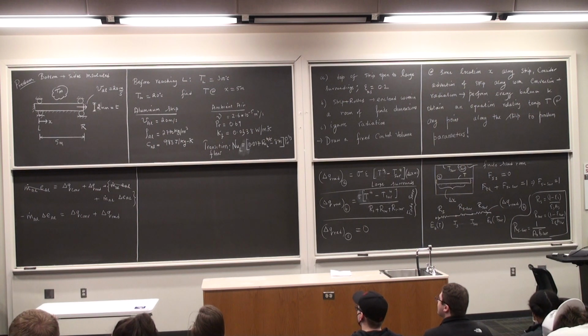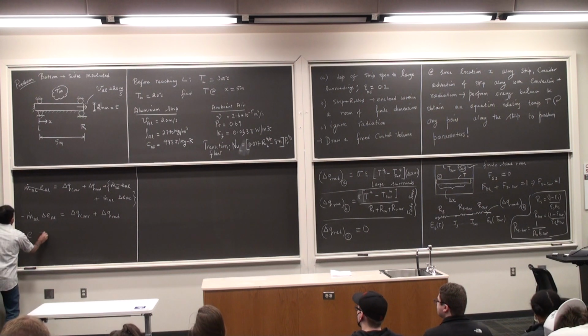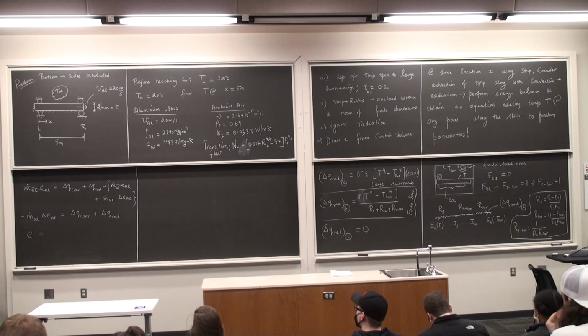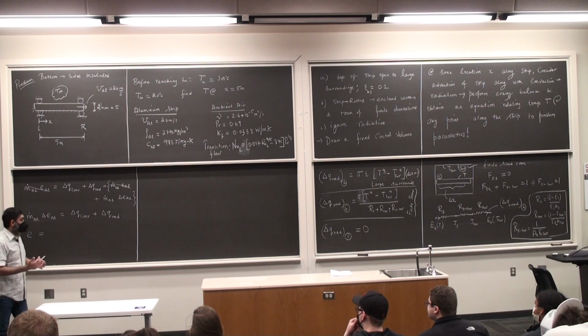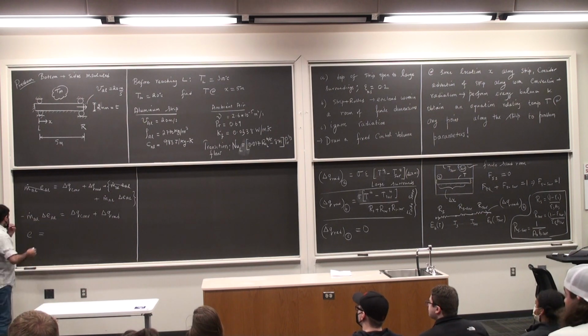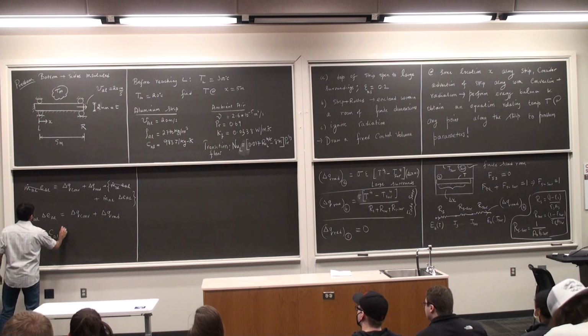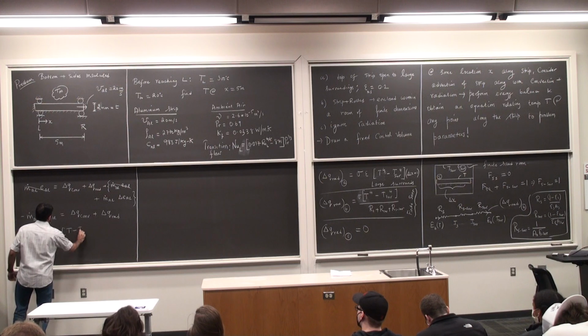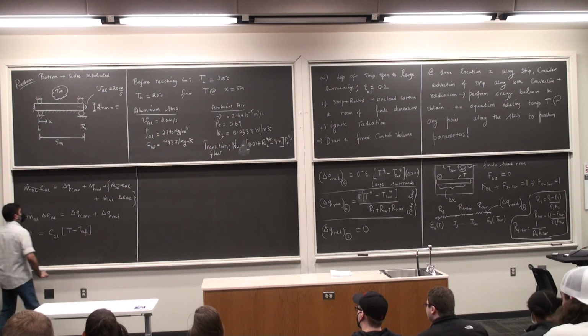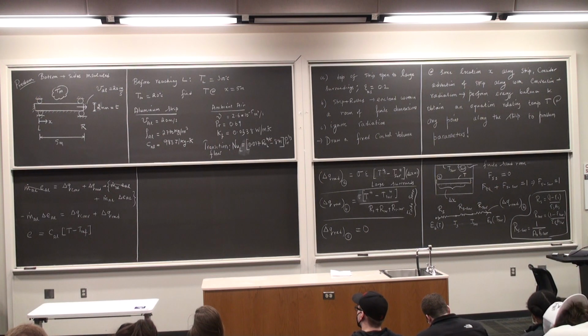When I reach the end point, we will make all these substitutions happen. So delta E AL, E by definition is the specific internal energy, so this is the internal energy divided by the mass. This is essentially going to be C times the local temperature minus some reference temperature. C is the specific heat of aluminum, which is given to us, 983 joules per kg Kelvin.